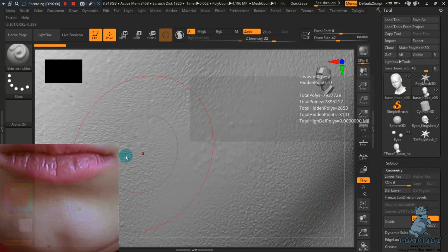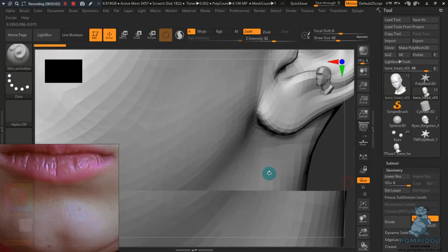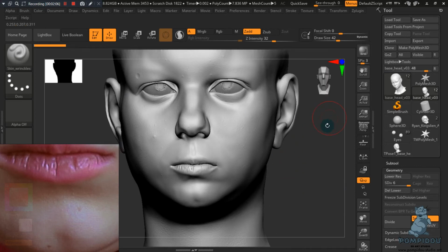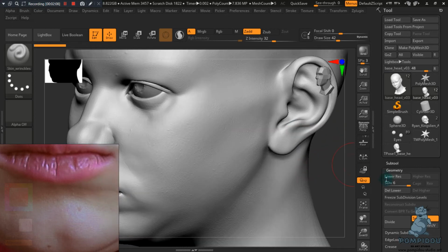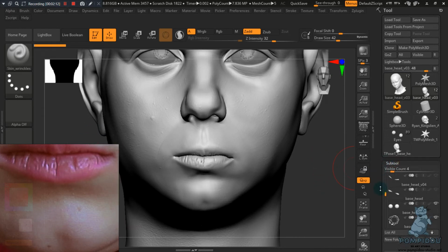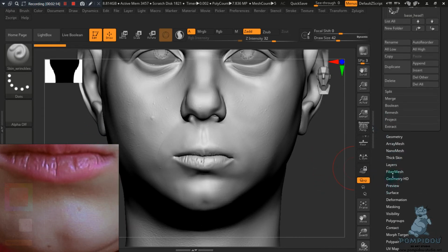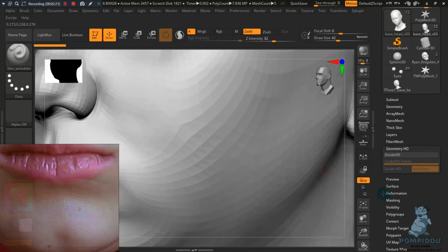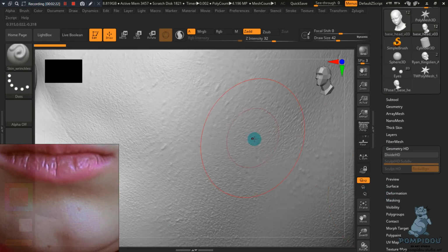In that case, HD Geometry lets you subdivide your mesh up to 1 billion polygons. You sculpt in a special mode where your system still runs quite fast but gives you a good resolution for sculpting. After you exit this mode, all data is stored in normal and displacement maps.